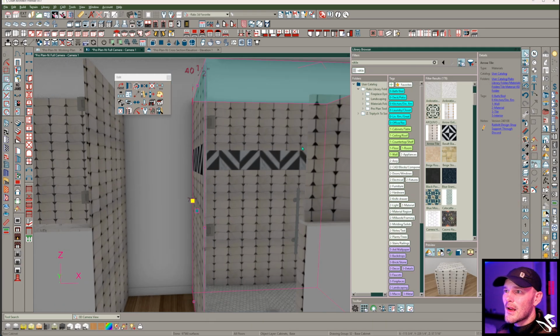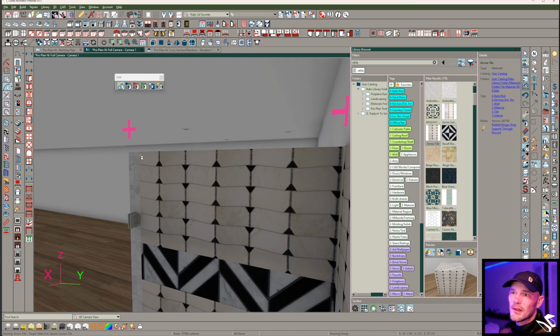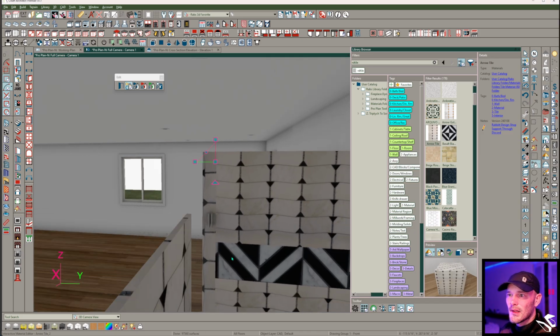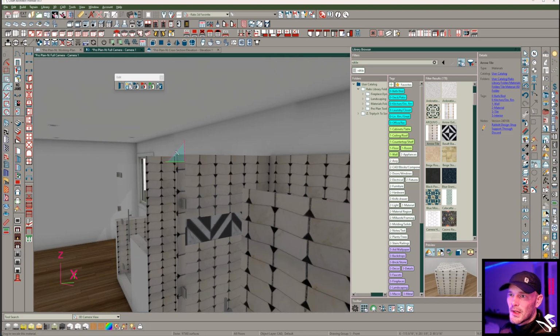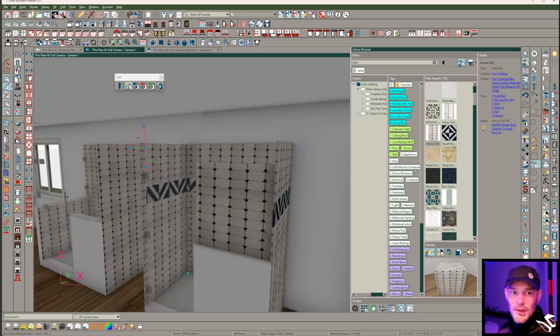All right. And now I get to create my little border tile. I can just paint like that. And then probably I would use the new interactive material editor in a component scoping mode, which makes a copy of the tile. And that makes it so that I can then just use the rotate handle. And while I'm rotating, I could hit tab or enter and say relative start 90 degrees. So that would be that border tile, and I can rescale it, etc. Right? So this is how we would do some more elaborate tile configuration pretty easily.